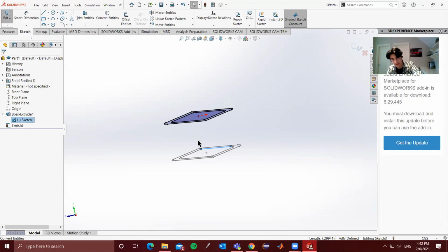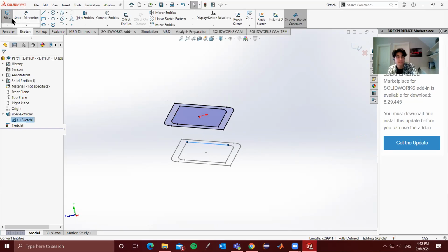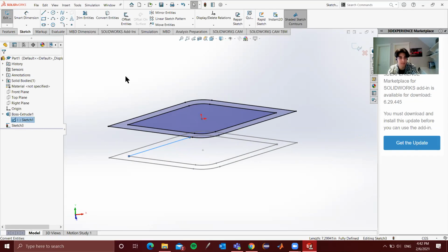If you had a diagonal line or a diagonal sketch, and your new sketch frame is not parallel to that, you're not going to take the full length and project it onto your sketch. You're going to have a portion of it, one component of your sketch, if that makes sense. So that's one feature that's pretty useful.